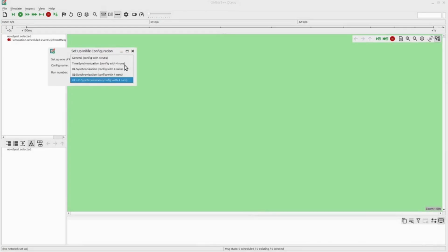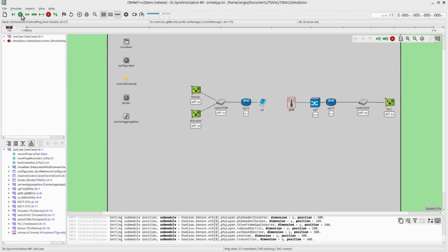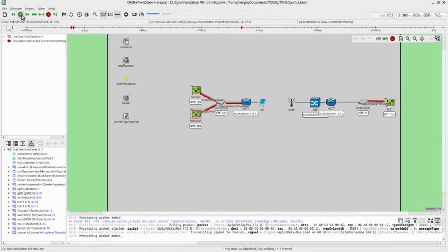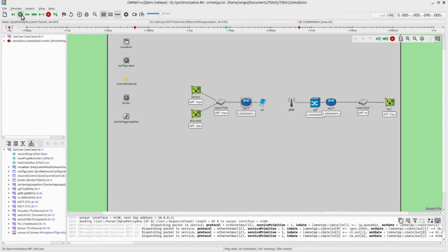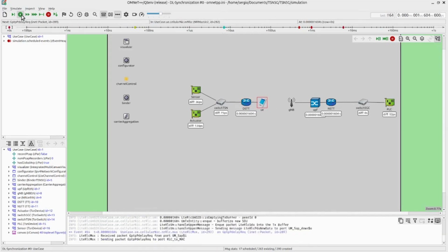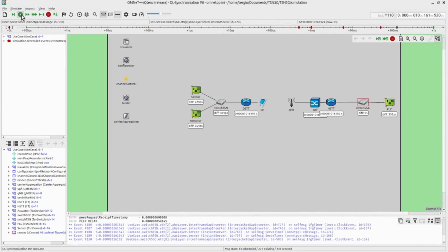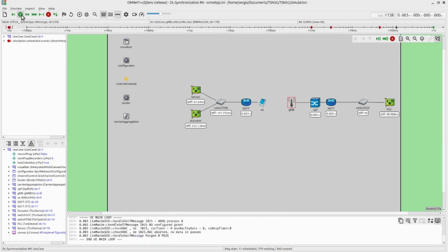Here we set which direction the time synchronization occurs inside 5G, by downlink, uplink, or passing between user equipments. We first chose the downlink case. In this case, the grandmaster is the node called switch 5GC, and in the beginning of the synchronization, all nodes calculate the period delay between the devices that will send synchronization messages.